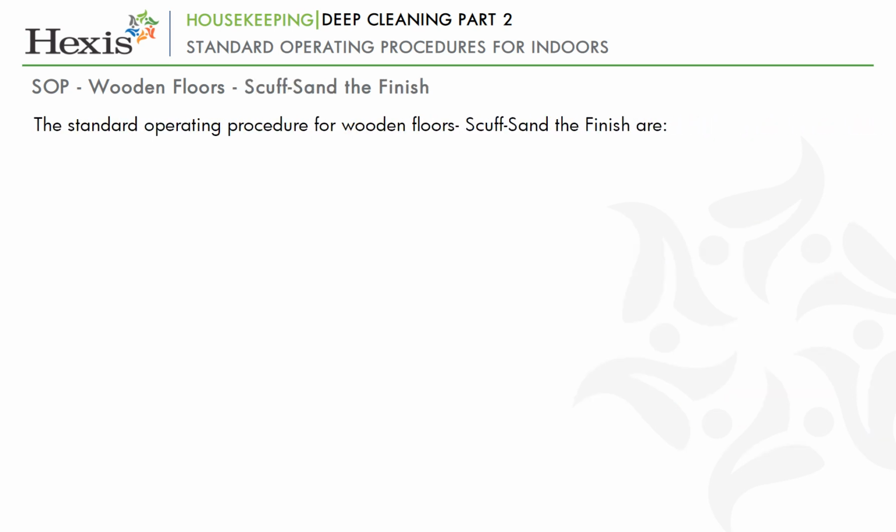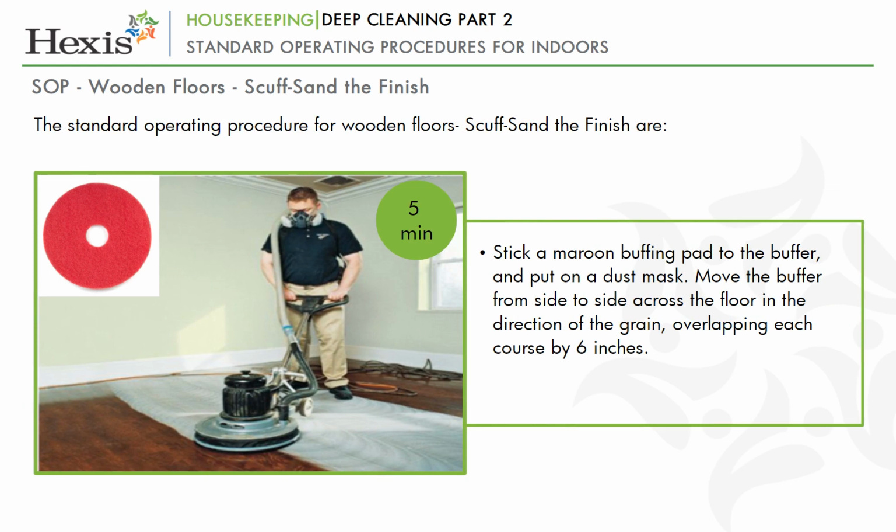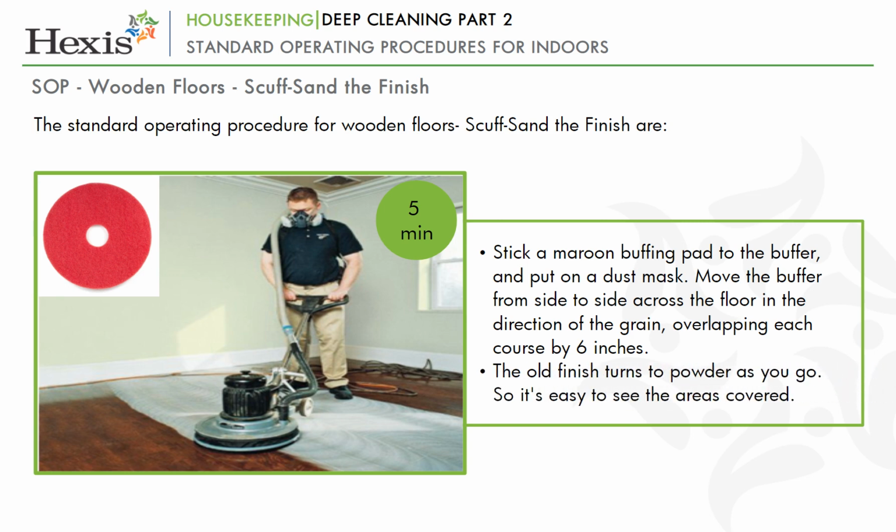The standard operating procedure for wooden floors, scuff, sand the finish are: stick a maroon buffing pad to the buffer and put on a dust mask. Move the buffer from side to side across the floor in the direction of the grain, overlapping each course by 6 inches. The old finish turns to powder as you go, so it's easy to see the areas covered. Keep the buffer moving at all times, but stop every 5 minutes or so and vacuum the pad.